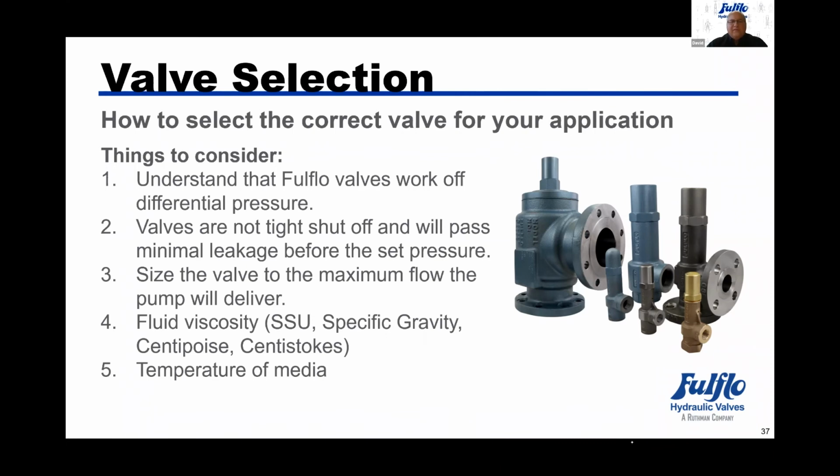One thing on the valves, they're not designed to be tight shutoff. They will pass a minimal amount of leakage before the set pressure. That is due to the fluid venting out the discharge, where water will vent out sooner because of the viscosity being lower than oil. It approximately is 10 to 15% below the set pressure at which the valve's going to start venting that fluid.